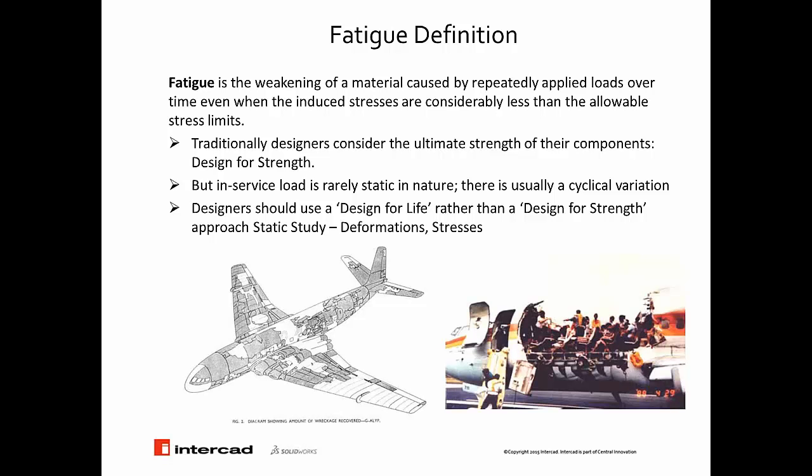Most designers consider ultimate strength for their components and they design for strength. That is good if we have just one loading scenario. But in real life, as all of our loads are cyclic or variable, then instead of designing just for strength, we have to consider fatigue and we have to design for life.